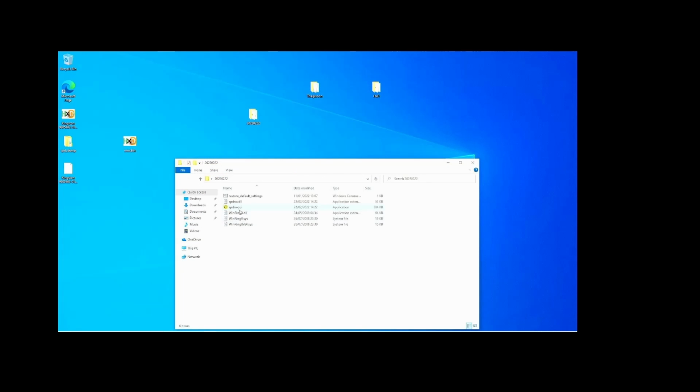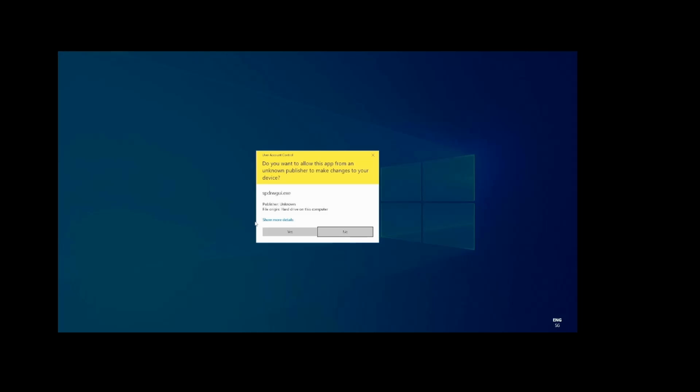I set up a rig where the chipset is supported. It's an old first gen i5 or something like that. And I want to show you here how to use SPD-reader-Writer when you don't have a flashing device, but rather use the built-in flashing over the mainboard, basically. And for that we want to start the SPD-reader-Writer GUI as an administrator.